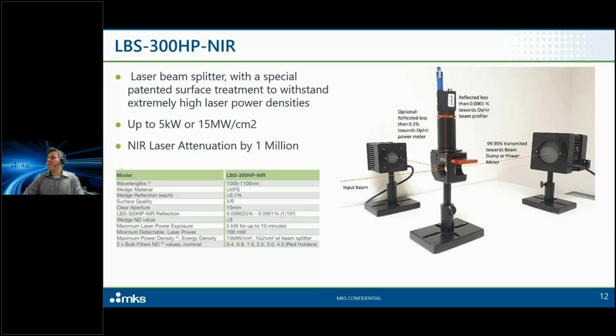Would it be more effective to apply blooming correction instead of Ultracal when optimizing beam profile accuracy, or does combining both yield a more precise and reliable measurement? Yes, definitely. You need to combine both the blooming correction and the Ultracal. Ultracal reduces the noise and the ambient light, and the blooming correction removes the blooming in the NIR region due to internal scattering.